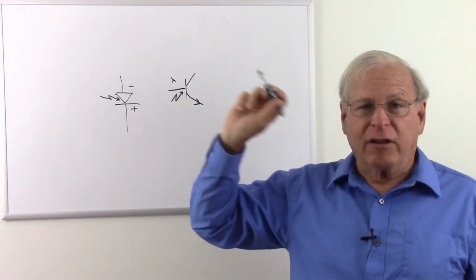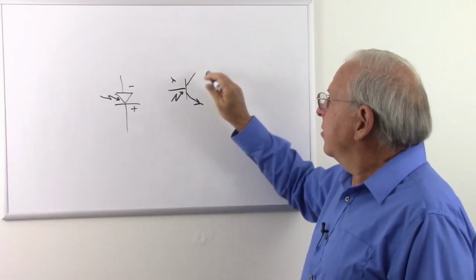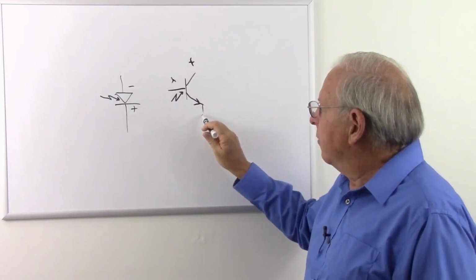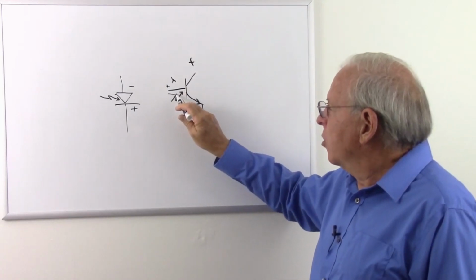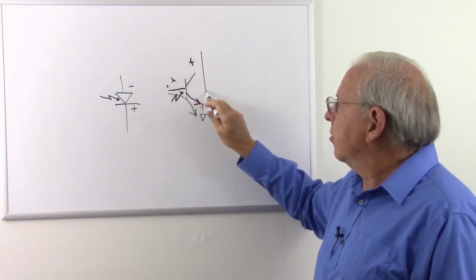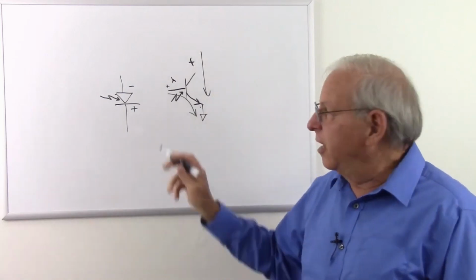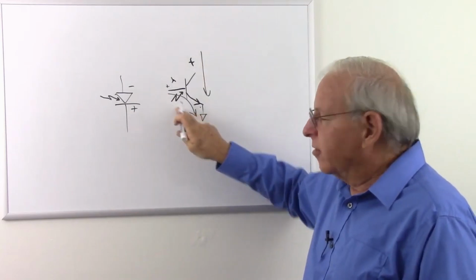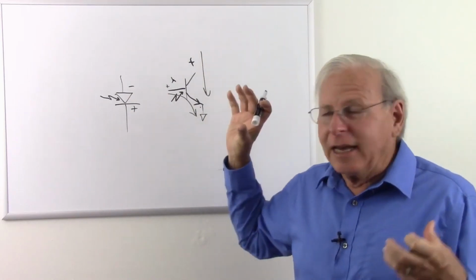Now, I'll talk about transistors in the solid-state devices way down the road, but basically we set this up with a positive voltage here, ground here, and a slight positive voltage there, and the more current we have go from the base to the emitter, the more current we have go from the collector to the emitter. And that's what our transistor does. Increase a little tiny current here, big current here. Make this bigger, this gets even bigger. That's how it amplifies.